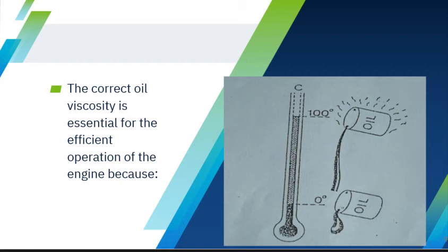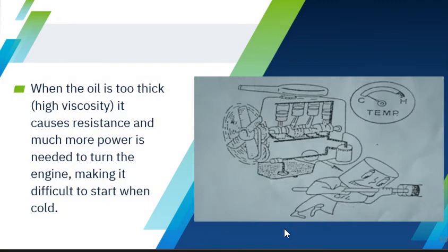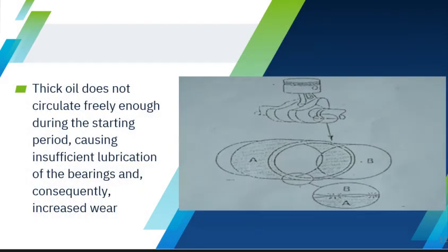Okay? Yes, it is very important because when the oil is too thick or the viscosity is very high, it causes resistance and much more power is needed to turn the engine, making it difficult to start when it is cold. Okay. For the motorists, they have experienced this one. And the thick oil does not circulate freely enough during the starting period, causing insufficient lubrication of the bearings and consequently increased wear and tear of the bearings.